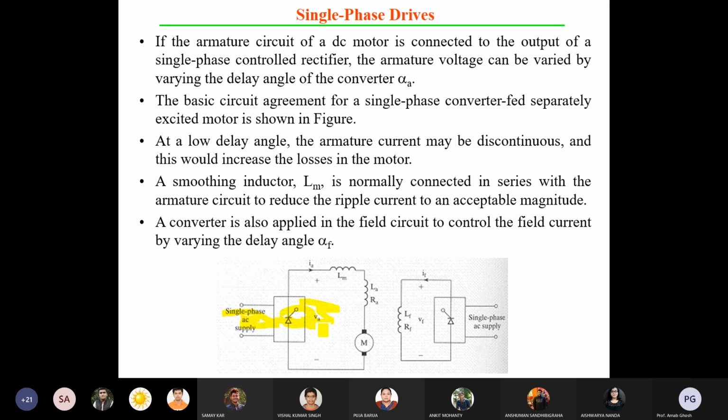If you are not able to control the firing pulse, you cannot regulate the motor speed. At the end of the day, whatever open loop system is working is fine, but you have to regulate the speed of the motor. Suppose current drives are using vector control mode for our locomotive service. If you are not able to control the firing pulse or the PWM width, what is the necessity of implementing them for this work? That is one of the important features. That's why, instead of a diode, we can use the SCR. That's the motivation for using the SCR compared to other devices.